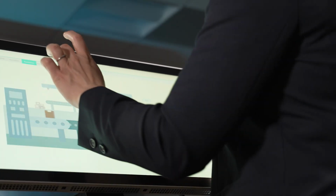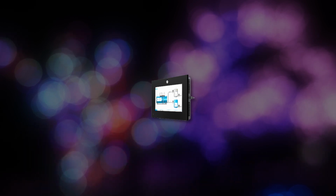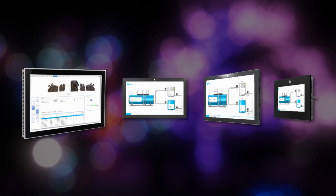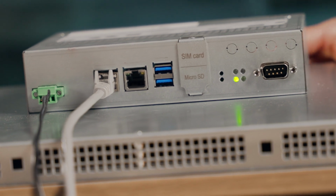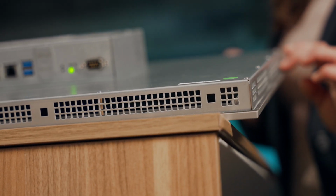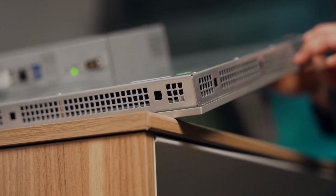OptixPanel's initial release includes two families. OptixPanel Compact has screens 4.3 and 7 inches wide and a single Ethernet port, as well as a serial port. In contrast, OptixPanel Standard has screens 7 to 21 inches and 2 Ethernet ports, so it can communicate on 2 networks at once and function as a bridge for FactoryTalk Remote Access connections. An IP69K stainless version is suitable for washdown.